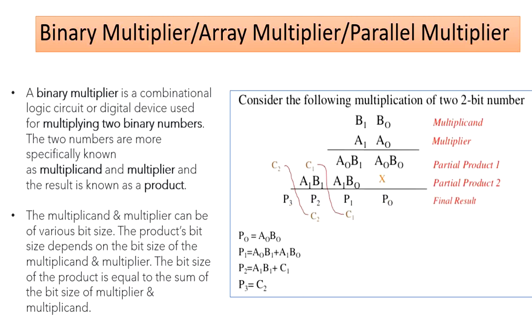Now as mentioned earlier, the binary multiplication method is the same as that of decimal multiplication. So binary multiplication of more than 1 bit numbers will contain 2 steps. The first step is a single bitwise multiplication, which is known as the partial product, and the second step is adding all the partial products into a single product.